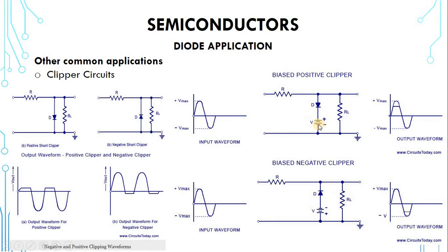With 3 volts introduced, the voltage developed here will be 3.7, so when the voltage goes beyond 3.7, current will start flowing through this arm and prevent current from going to the load to damage it. By so doing, we increase the level of voltage that can be clipped.